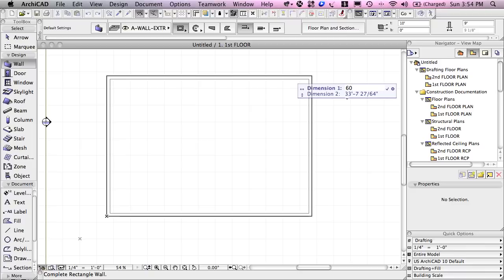Sometimes it's good simply to draw or gesture with your mouse, like I did, and see what ArchiCAD is showing you, because then when you type in something, you'll know whether to type in, for example, this would be 20 meters approximately, but are you going to be typing in 20, or 2,000 centimeters, or 20,000 millimeters? Which one is it set up for?